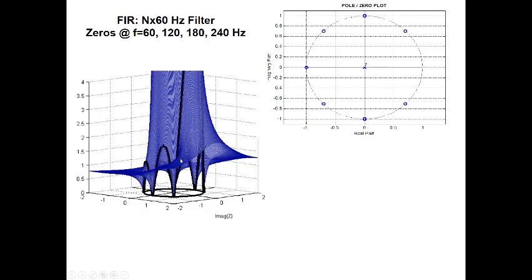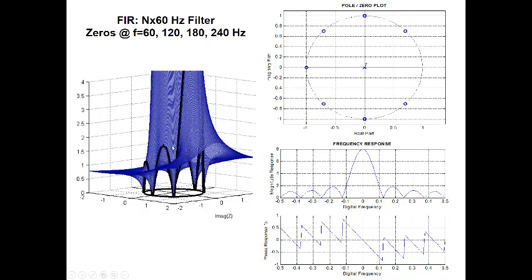They're a bit narrower, but I've also got some kind of weird shape in my magnitude response. Because I don't have a 0 over here at DC, I don't have things kind of equalized, and so there the gain is allowed to go up really high compared to the other locations. So that's not quite going to work. We still have linear phase, so that looks all right.